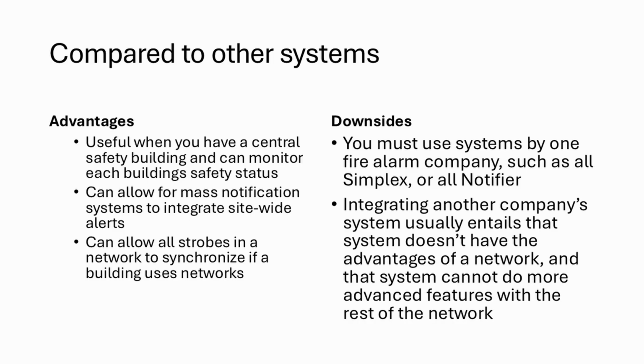The downside, you must use systems by one fire alarm company, such as all Simplex or all Notifier. And integrating another company's system usually entails that specific system lacks the advantages of the rest of the network, and if that system is currently active, it cannot communicate with the rest of the network.